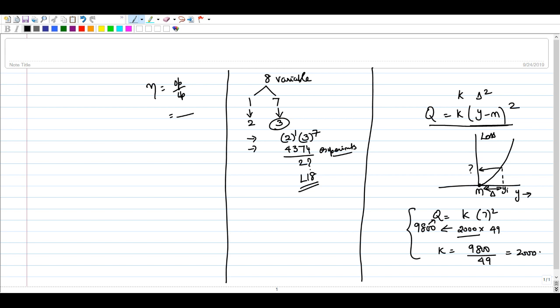And how does one get the minimum number of parts? It is based on the three criteria that we have discussed. The first criterion is that the part moves relative to other parts during the normal operating mode. So for a proper operation, if a part needs to move with respect to the other parts, that is one case. Then only can it be considered as a part.